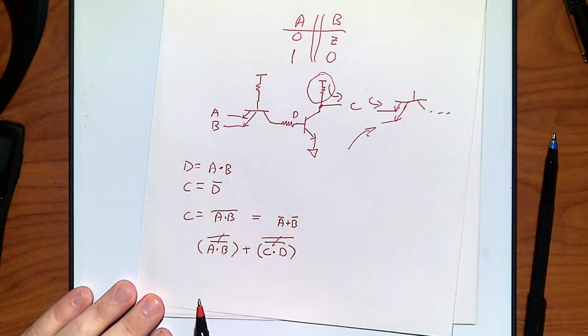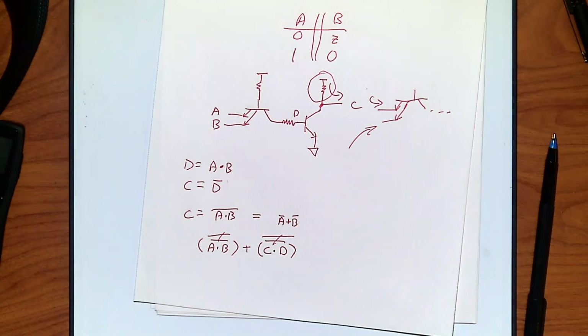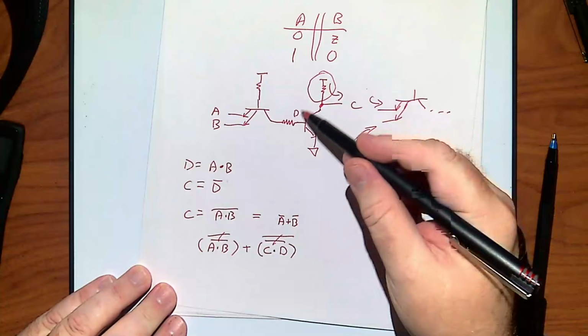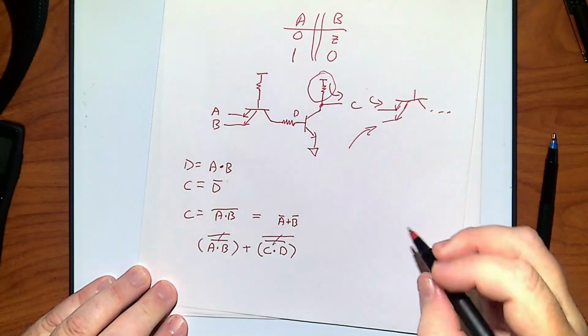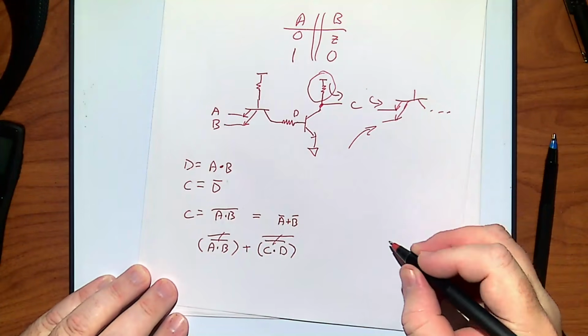All right, so we've got these. Let's say that I don't want to supply power here, but I want to have a better output. This gets to be what we're going to call totem pole. So now we're going to, in essence, do a push-pull type system. I want a separate thing to switch power and another one to switch ground. So we're going to take this area here and consider the switching ground.